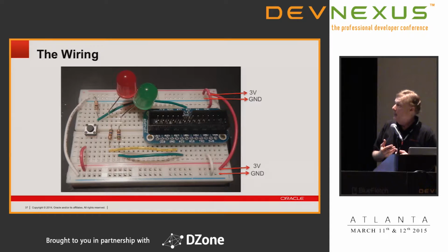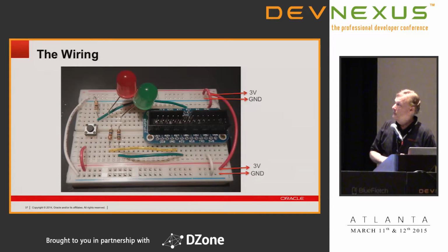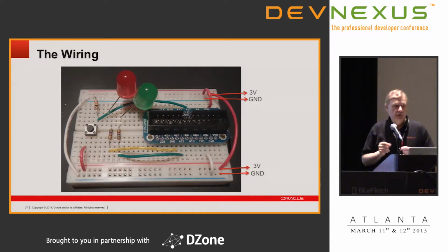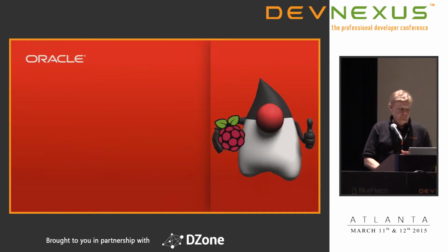So it gets a little bit more complicated. Taking a look at the breadboard, up at the top, the top 2 rows and the bottom 2 rows are all connected horizontally, and that's how you can easily connect things together. And then the 10 rows, 5 and 5, in the middle, those are all connected vertically so that you can hook things into them and connect them without soldering things together. That's the real reason you use breadboards. You don't want to solder things together prematurely. And so that's what the wiring for this project looks like.